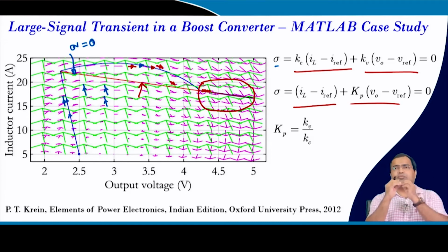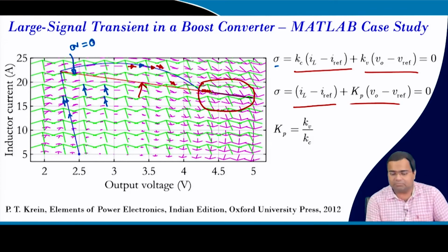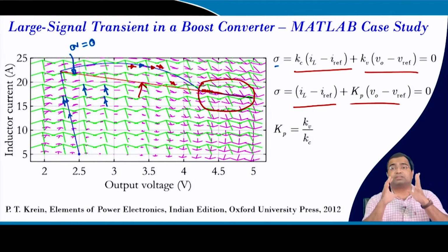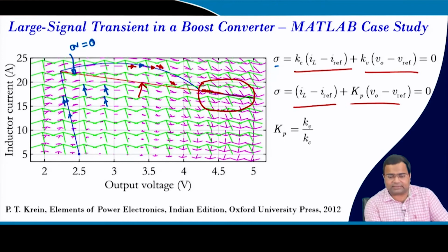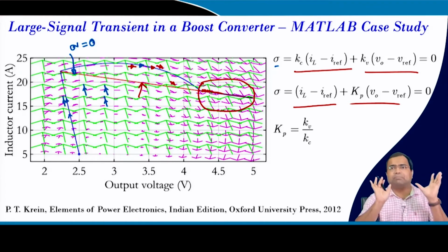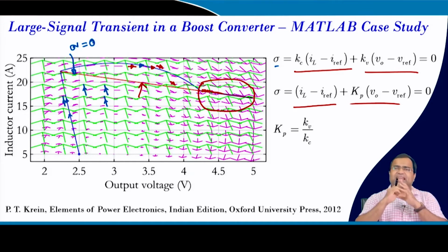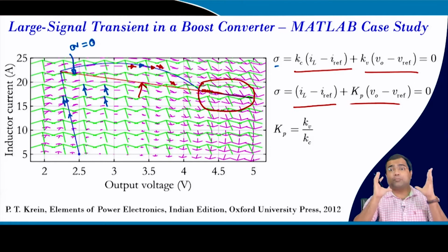That means the ripple is almost not visible, but it is actually going, and this concept is similar to the sliding mode control that we learned in lecture number 45. Now, we discussed the surface, but there has to be some band, otherwise your switching frequency will be extremely high, which is practically not feasible. Your device will not operate, or it can even get damaged.